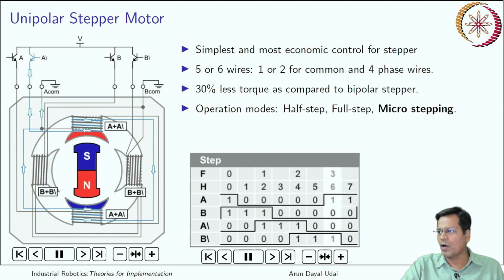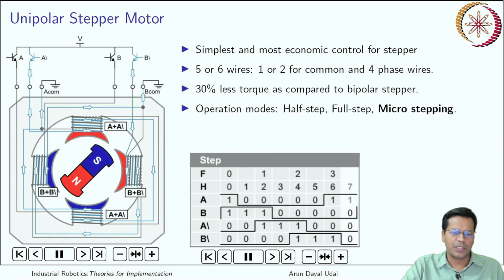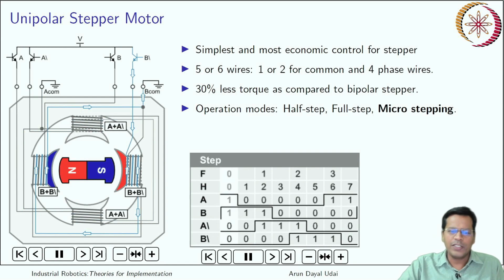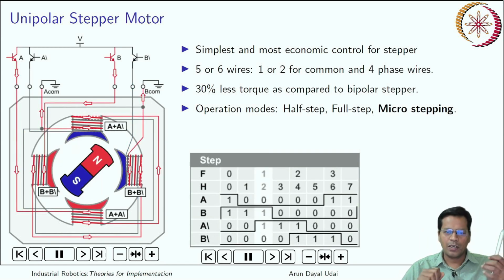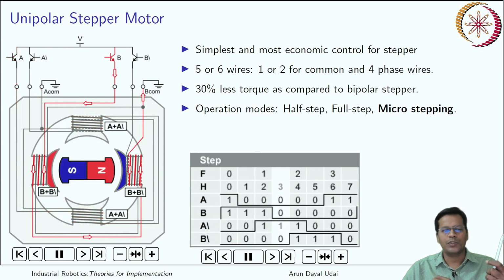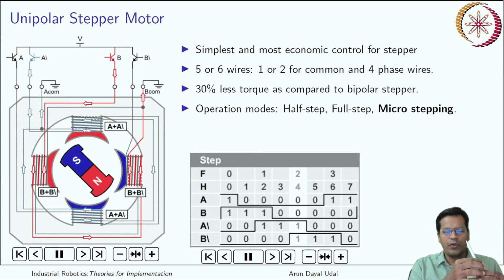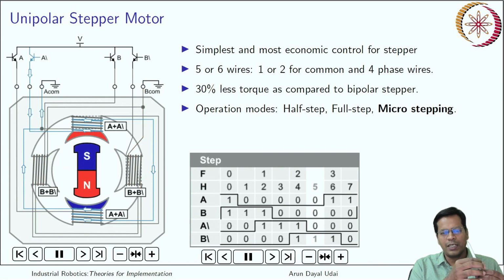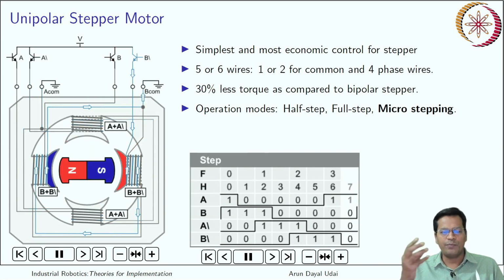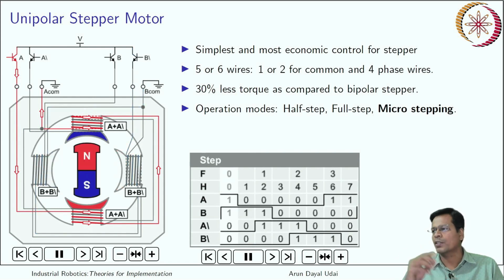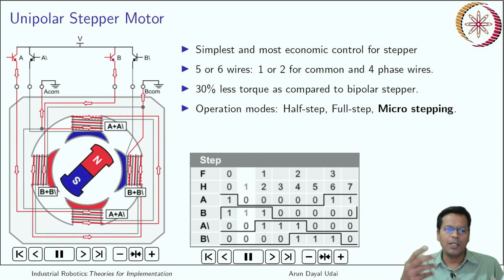So this is how your stepper motor keeps running. For every pulse set to all the 4 wires, your armature is at a particular position, and then with the next pulse sequence it is at a different position, and so on. Every pole has got double winding.